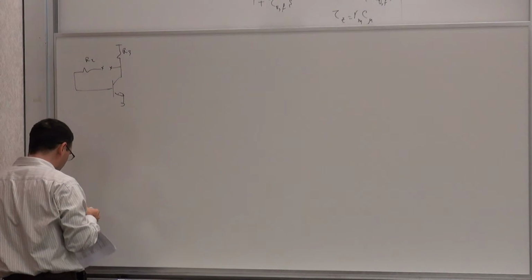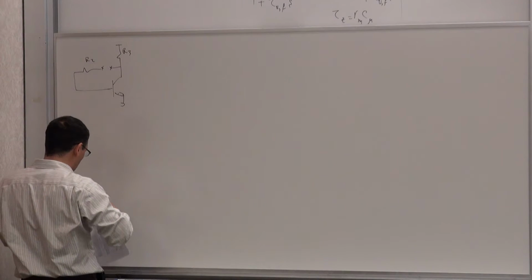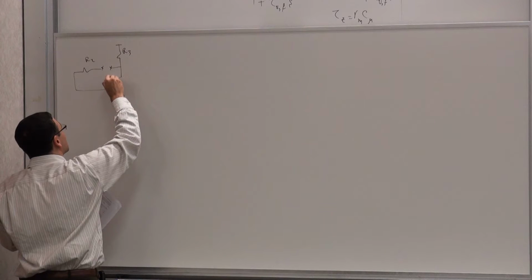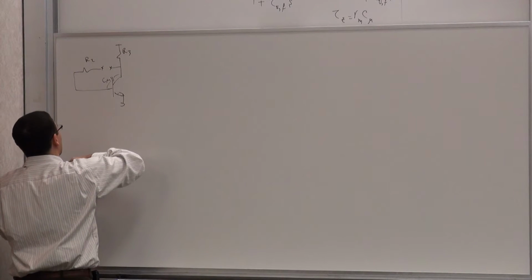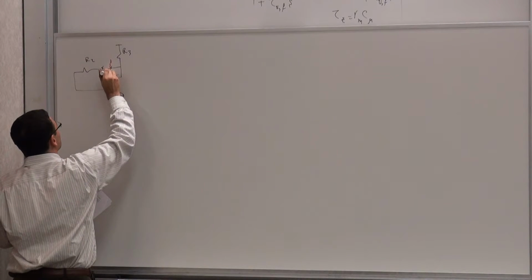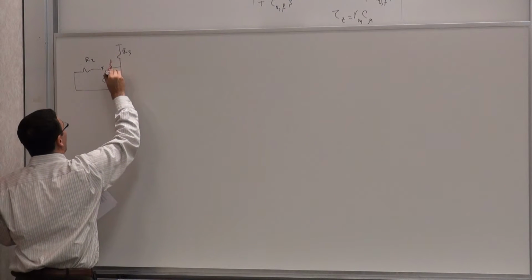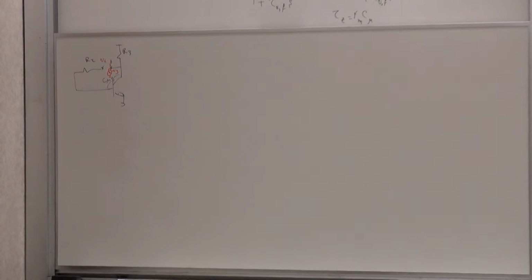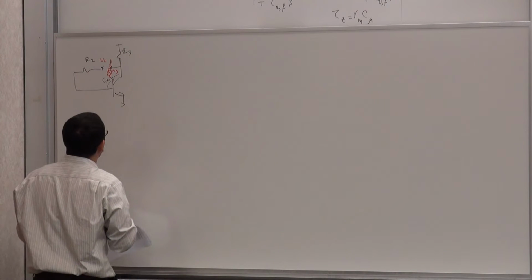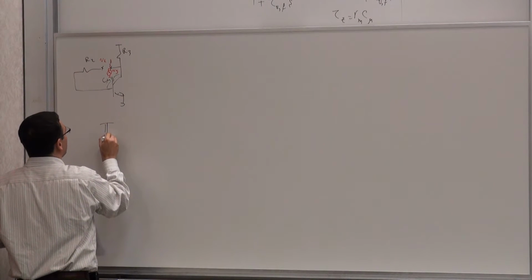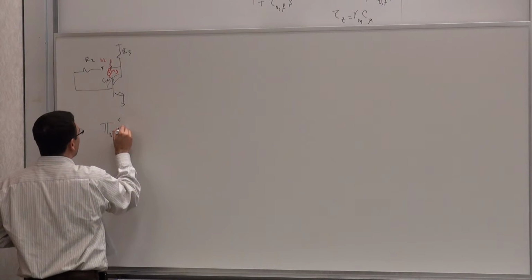So for calculating the reverse loop gain, now I have to apply a voltage. So I can apply a Vx here, or Vy here, sorry. Vy, and measure Vx. So what is that transfer function? Well, let's find out. So what is T_V reverse 0 when C_mu is 0?